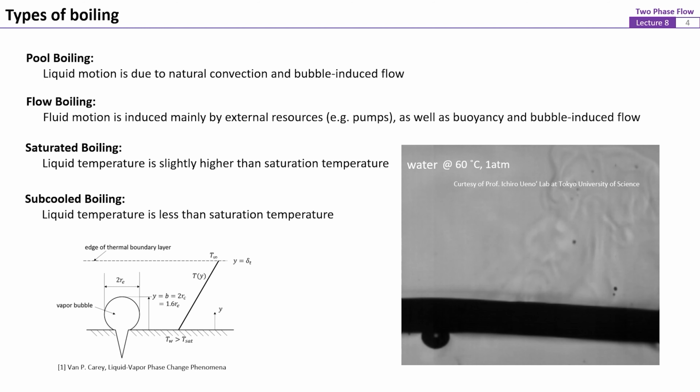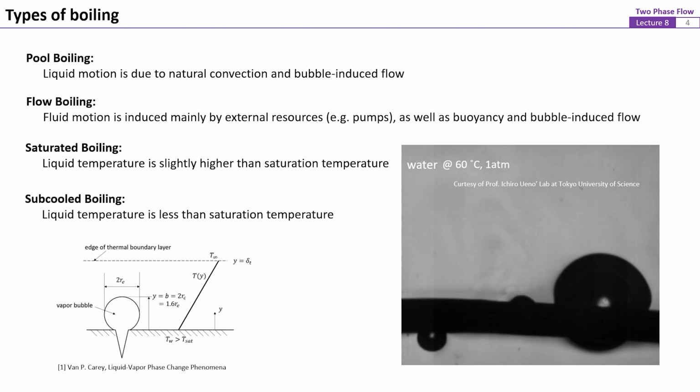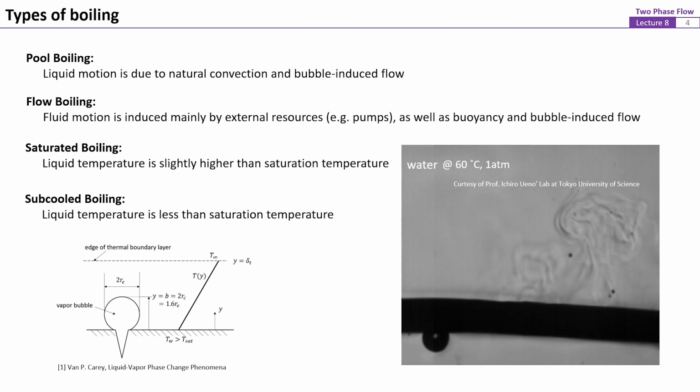As can be seen, the bubble forms on the surface of the heating wire and collapses rapidly. Upon the point that the top portion of the vapor bubble is beyond the thermal boundary layer near the heating wire, the vapor bubble is in contact with the subcooled liquid. Heat is transferred from the vapor bubble to the cold liquid through the interface.